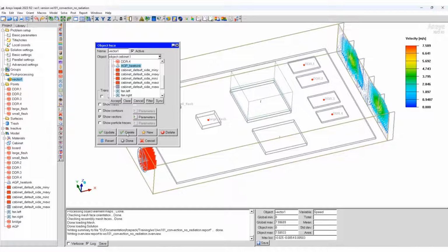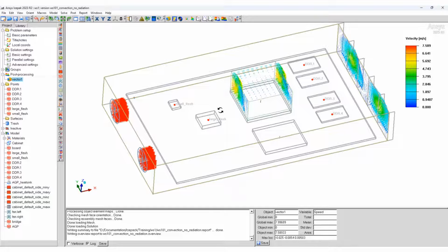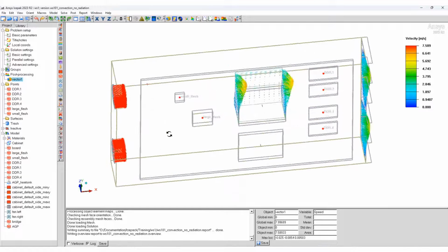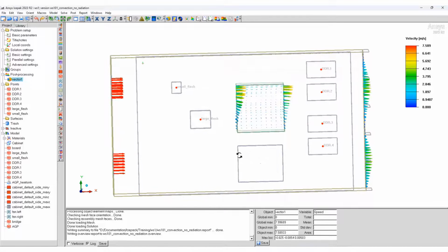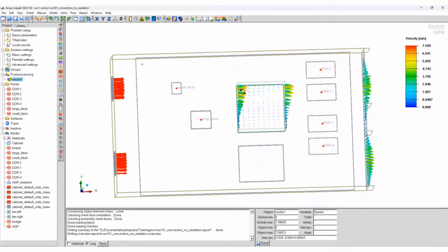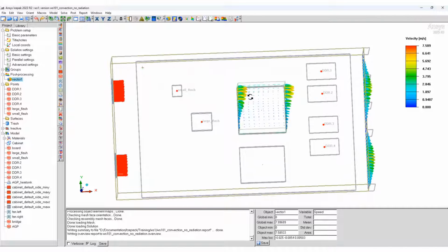Done. So you can immediately see that the heatsink is receiving non-uniform velocities. You have much higher velocity or flow through the heatsink on the upper side, that is in the positive y-axis side, compared to on this lower side. So essentially, this will immediately lead to a higher temperature on this side compared to the lower temperature on that side.